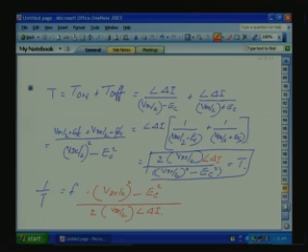So, what is the purpose of deriving this equation? I have brought the hysteresis band, that is delta I, into this one, and related it to the PWM switching frequency. So, this equation shows that for a particular delta I, for the inverter, VDC by 2, the DC link, is fixed. Assume for a DC motor, if EC is fixed, then the frequency is related to delta I. Okay. So, what is the relation? Again, we can rewrite this in a different form.